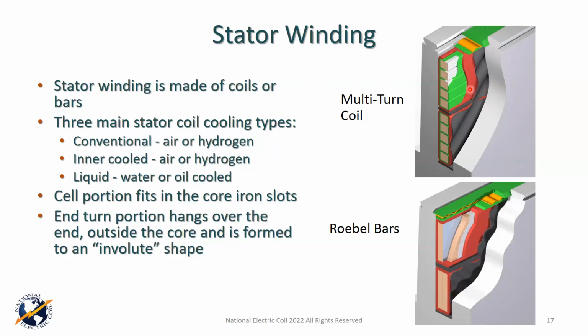There was a question early on: when you're choosing and planning a rewind, one of the key things to put in there is, today, I would say most standard is 65 volts per mil or less. In the hydro world, the Bureau of Reclamation and the Army Corps of Engineers push really hard with very tight specs on coil manufacturing, and they usually require less than 65.